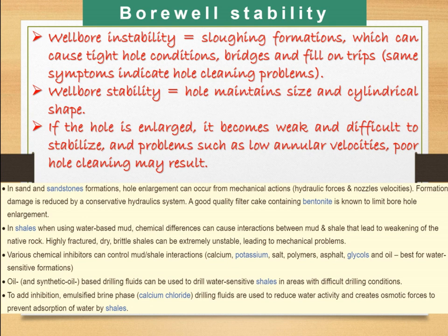For example, in sandy or sandstone-rich formations, hole enlargement often can occur from mechanical actions like hydraulic forces and nozzle velocities. So formation damage is reduced by a conservative hydraulic system. A good quality filter cake containing bentonite is known to limit borehole enlargement in case of sandstones.